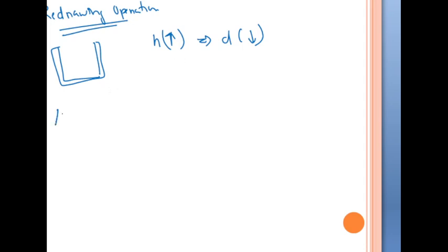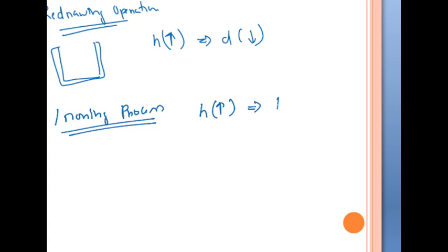Now ironing process. This is also a deep drawing process, a sheet metal drawing operation. What will happen here is that the height, that is the depth, of an article which is already produced by deep drawing operation will be increased at the cost of decrease in thickness.